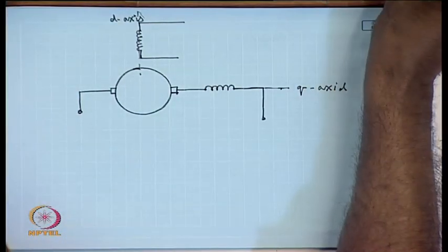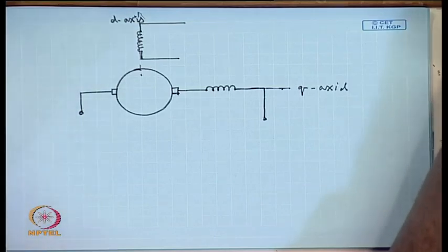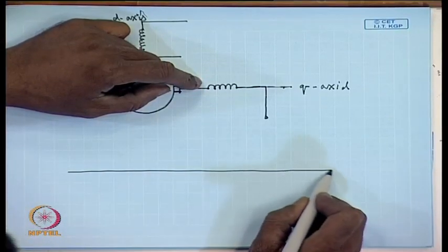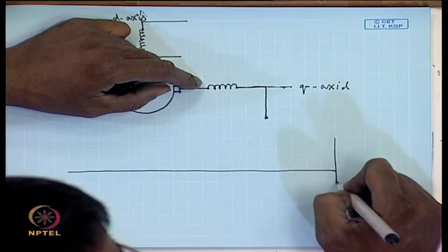Once the compensating winding is in place, it will cancel mostly the armature MMF flux directly under the pole, but it will not compensate completely the MMF at the interpolar region. Therefore, the armature MMF with compensating winding will look somewhat like this.